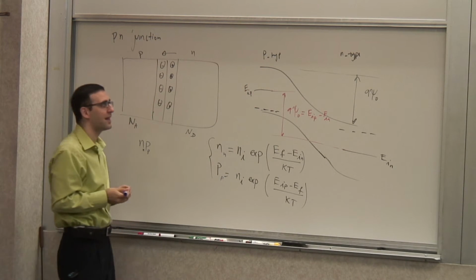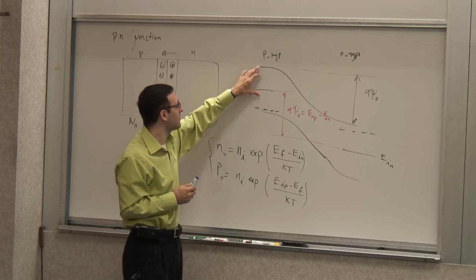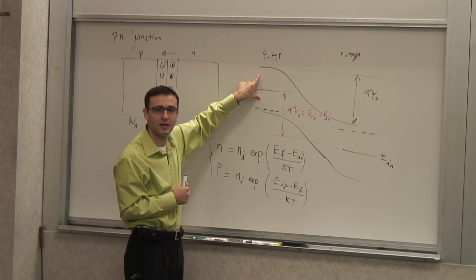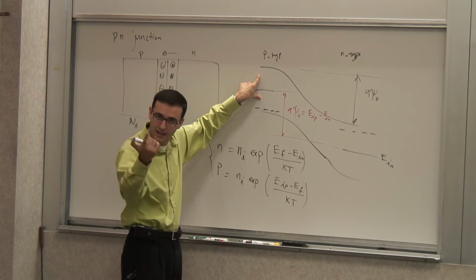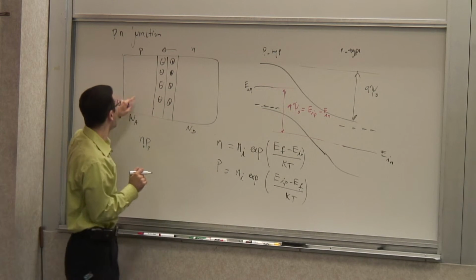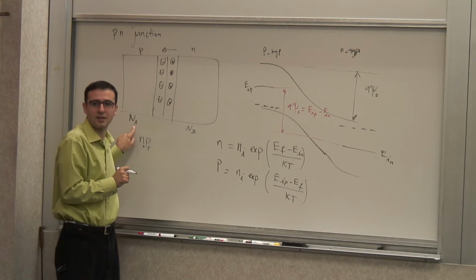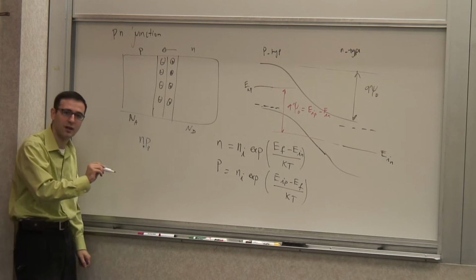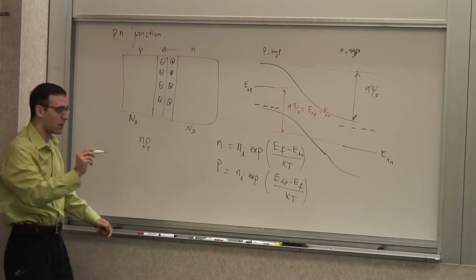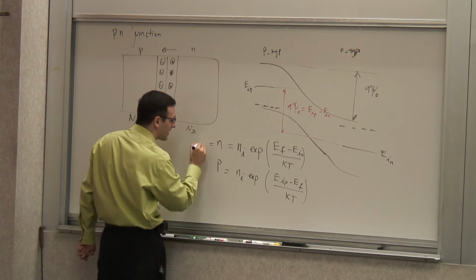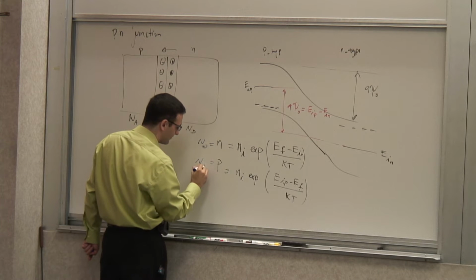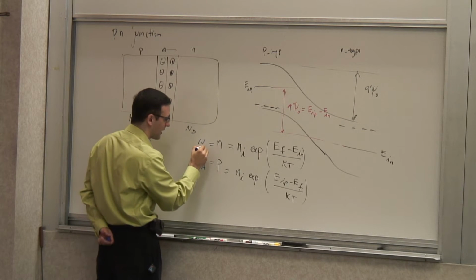So actually, let's talk about that for a second. What is the P? What is the concentration of holes on the P side at room temperature? Na, exactly. So I know that all of my acceptors will be ionized at that level, and we saw that nice little curve, right? The temperature that we went up first, and it became flat, and then it went up again. So we are in the middle range. So that's the beauty of it. So I can control this. Well, this is Na,